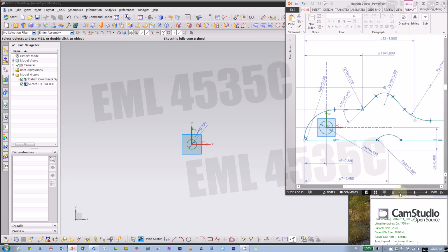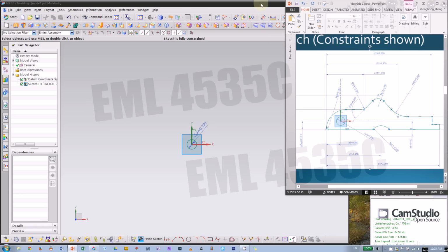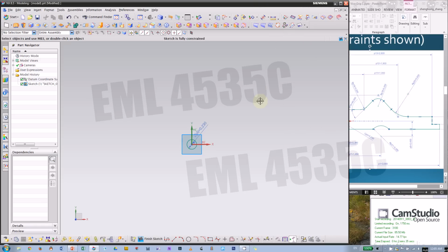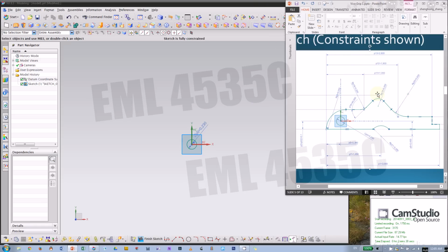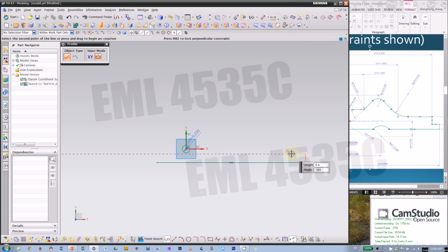Okay, so with that in mind, we can start this sketch. And here I need to say this again: in computer drawing, in CAD, you don't have to follow the dimension at the beginning. All you need to do is have a general geometry of the sketch. So here's what I'm going to do. Use the profile tool, and I don't worry about the dimension right now. Since I have the first circle that's up to scale, I know about how much I need to draw. And I can start drawing.